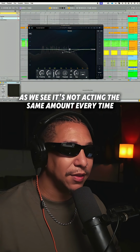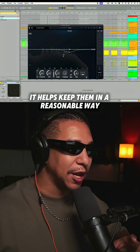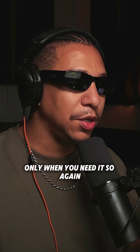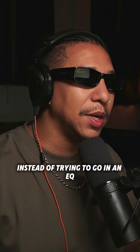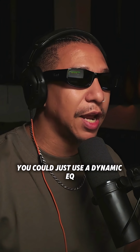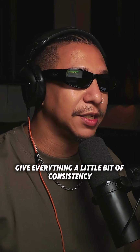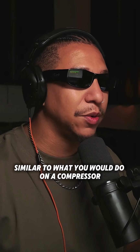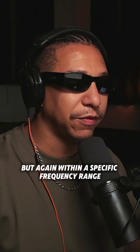As we see, it's not acting the same amount every time. It helps keep them in a reasonable way in the specific frequency that you have it set to, only when you need it. So again, instead of trying to go in and EQ all of the vocals separately to try to get them to match each other, you could just use a dynamic EQ, give everything a little bit of consistency, use a dynamic EQ to control those peaks on a vocal, similar to what you would do in a compressor, but again, within a specific frequency range.